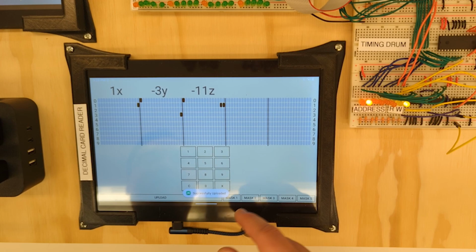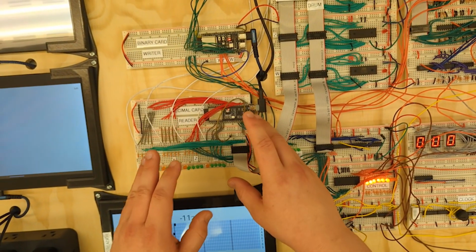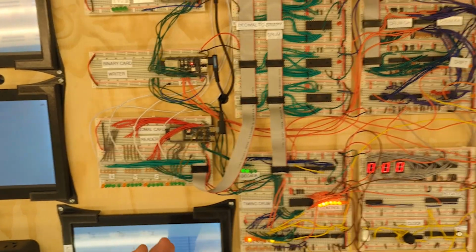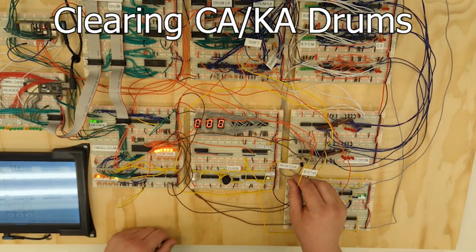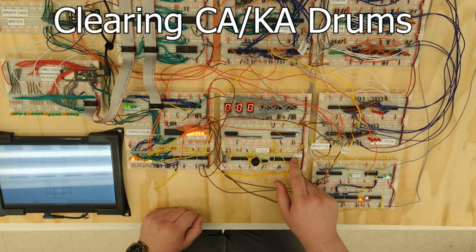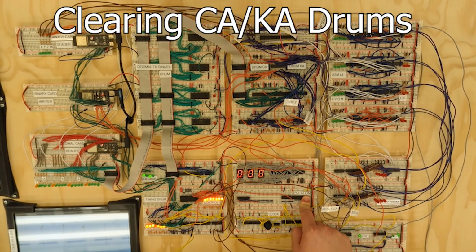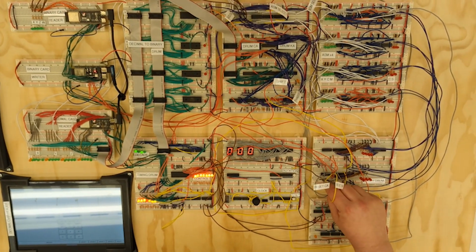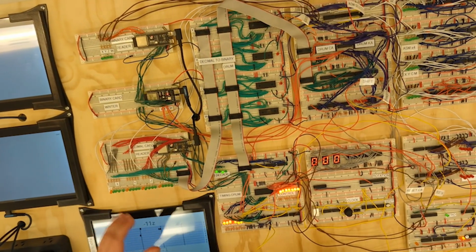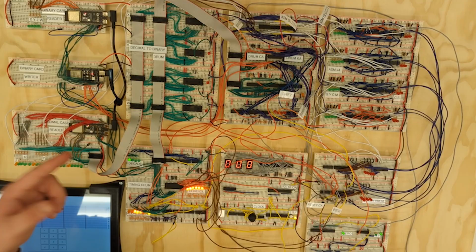So once we see it is connected and successfully uploaded, we know that we have entered that data. So that data is currently being held by this ESP module, but it will not output anything until this wire is pulled high. Before that, we need to clear the drums. So we'll take our reset CA and reset KA flags, pull them both high, and we will step through a full cycle of the drum, just to make sure that all data is erased from them. Then we pull them low, and we can pull this high to enable the ESP module. And now we need to step through cycles until this decade counter resets to 15.